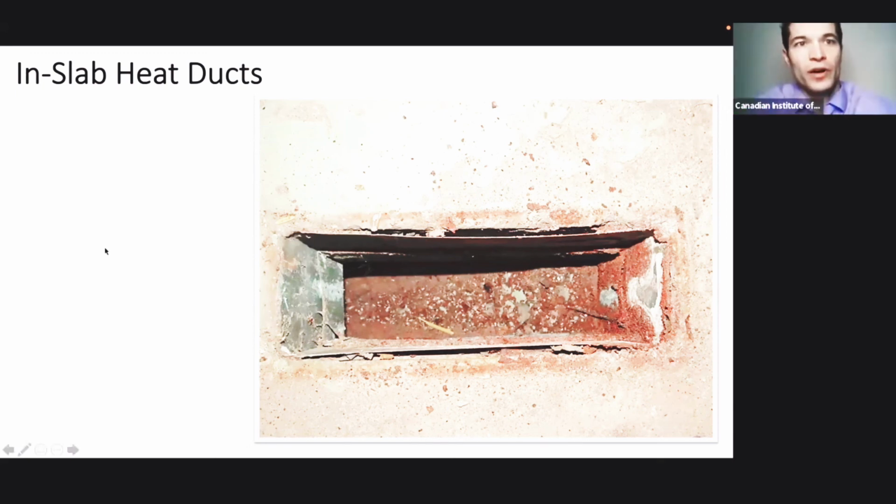Yeah, if you come across these in-slab heat ducts, be sure, if you can, to actually pull up the register and look down, because like Sam said, if you see any standing water, any corrosion, any debris, you definitely want to point it out, because usually there's no point in repairing the systems. Usually they'll just terminate it, flood the ducts, and have a typical conventional system where it runs through the ceiling.